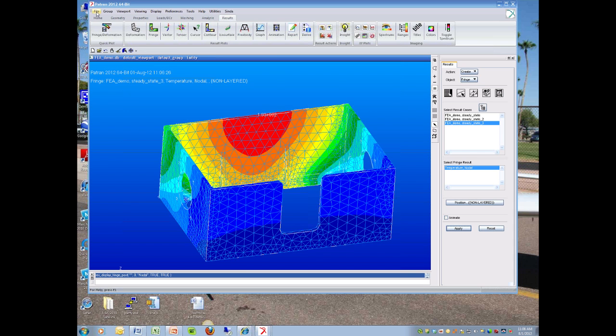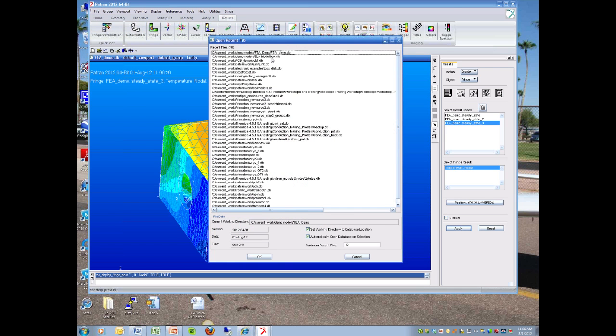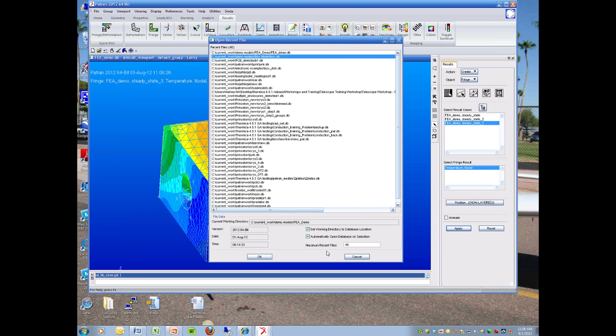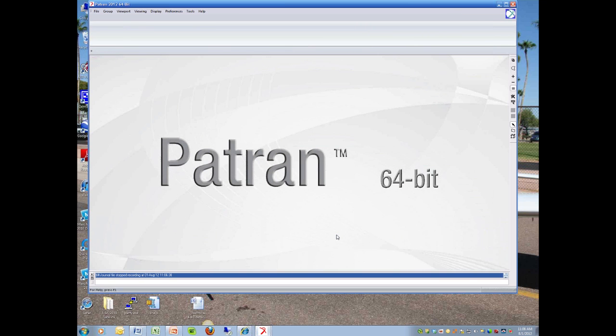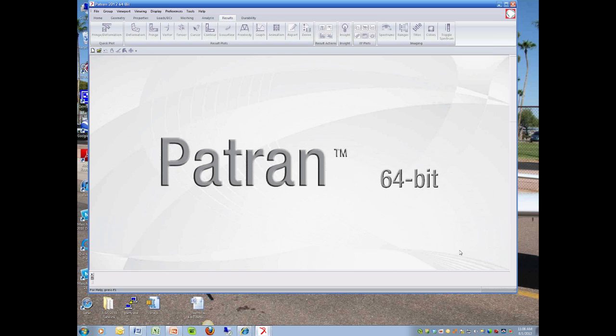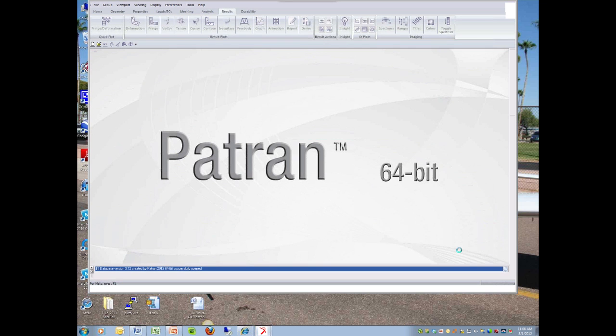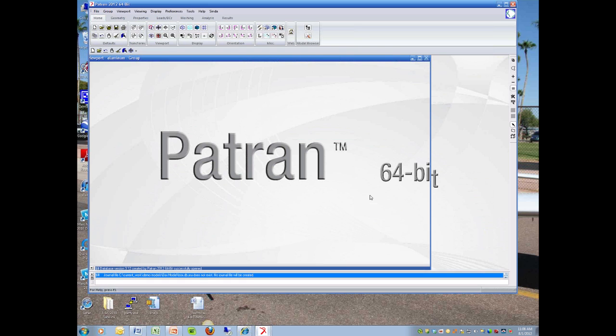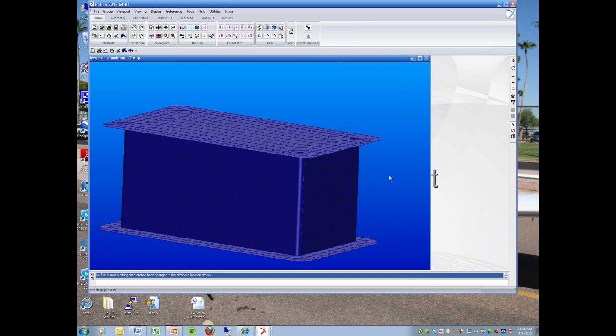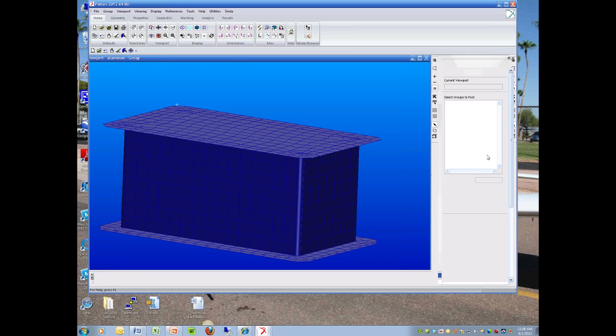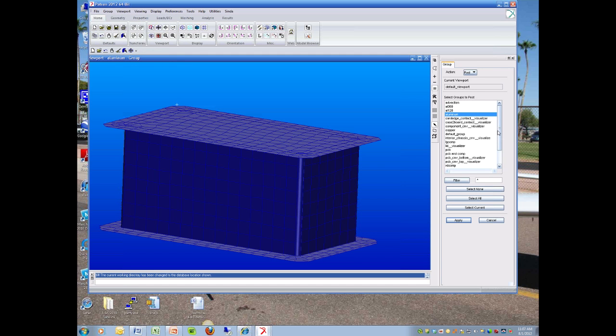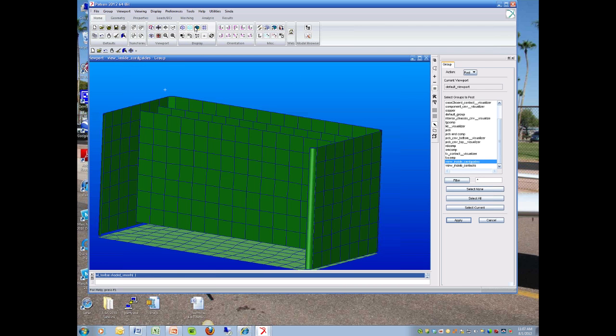This model. And then quickly, I'm just going to show you this other box with PC boards in it so you can see what that looks like, and then we're finished. So this is a little more complicated box level model. You can work at a component level, you can work at a board level, box level, or even a whole aircraft like a J-Star sort of plane full of racks of equipment and airflow through all these racks. So I've made a lot of groups here on this model, and I can look inside of it. I've got a group that lets me look inside and see what it looks like.